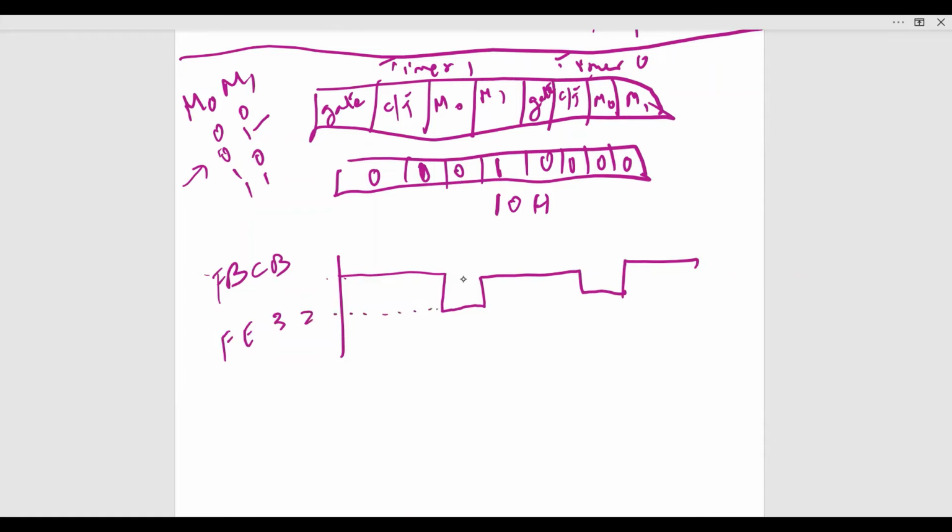So we have converted time into hexadecimal. And then the TMOD register, we have to initialize with 10. And then we can use any port to look at the output waveform. So these are the points you have to remember before going to the program.